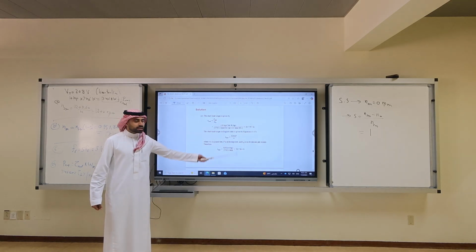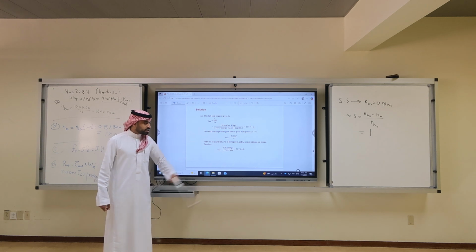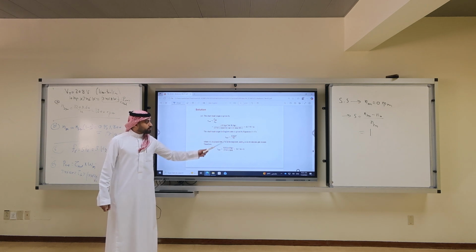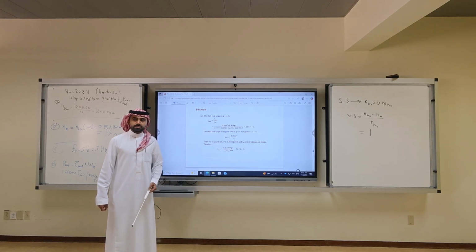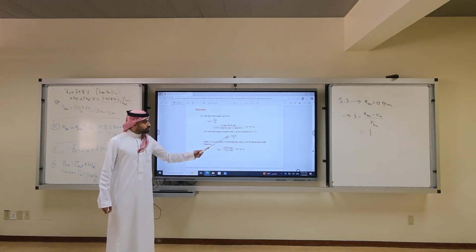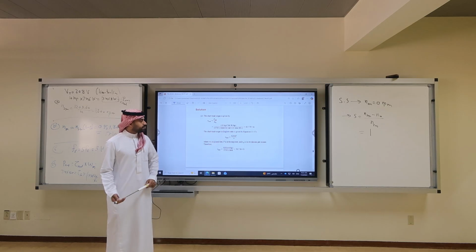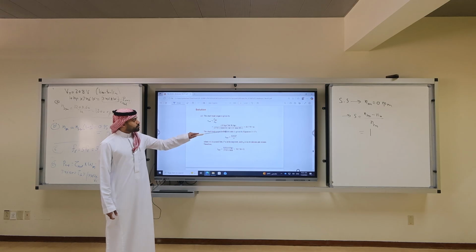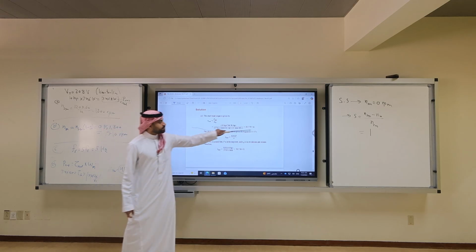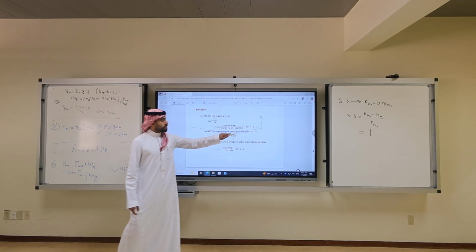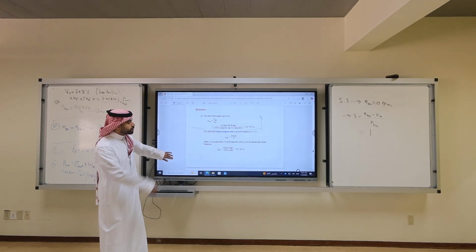Also, he is showing you another formula to get the shaft torque using pound times feet. If you want to do your masters in the UK, you might deal with this, I don't know. But you can use this formula to get the torque in pound times feet, which is 5252 P in horsepower over N. But what matters is anything above. Anything below not required, but this is for your knowledge.